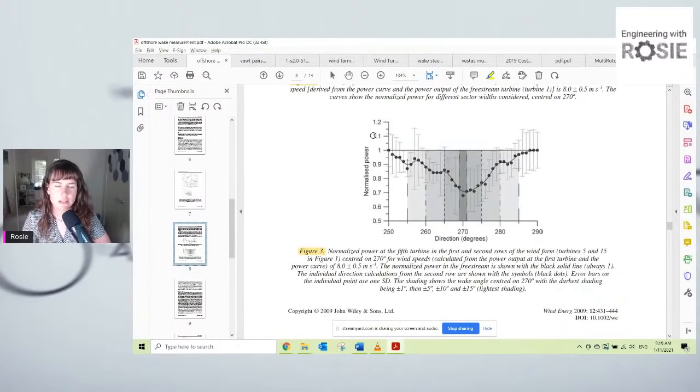So I just wanted to mention that this effect is significant and it's big and people care about it, but it's maybe not as big as it first sounds, because one, it only matters up to the rated wind speed. Once you reach the rated wind speed, then the generators are going at their maximum amount. There's excess energy in the wind that they could never deal with, no matter what they were seeing. So the issue goes away once the wind speed gets high enough.